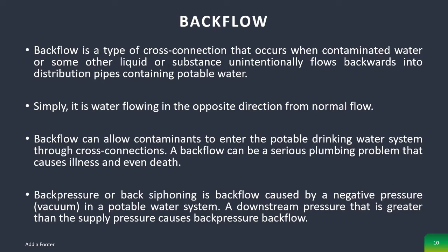Simply, it is water flowing in the opposite direction from normal flow. Backflow can allow contaminants to enter the potable drinking water system through cross-connections. A backflow can be a serious plumbing problem that can cause illness and even death. Back pressure or back siphoning is backflow caused by a negative pressure in the potable water system. A downstream pressure that is greater than the supply pressure causes back pressure backflow.